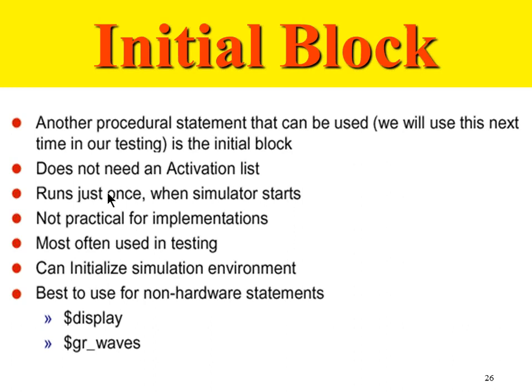The logic that gets executed on power up or reset condition is where the initial block comes into the picture. All the logic that I need to execute on power up, I can put in the initial block. When I reset my system, the initial block will execute its logic and then it will go to the rest of the design after that block execution is over.